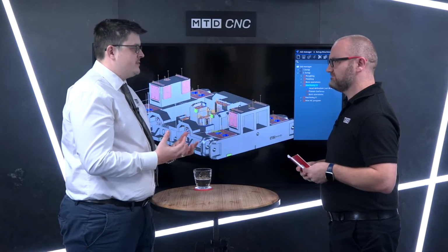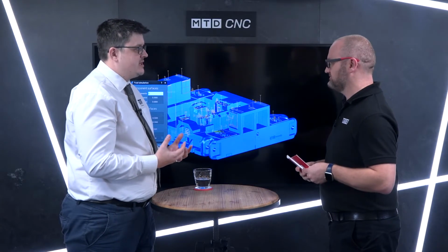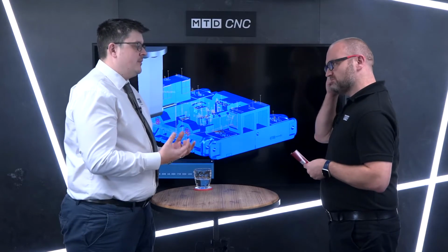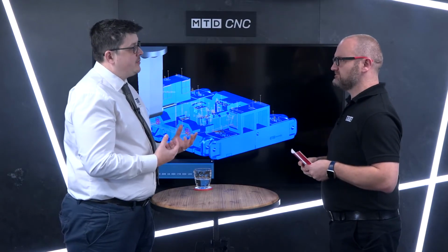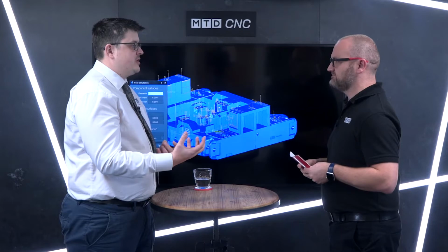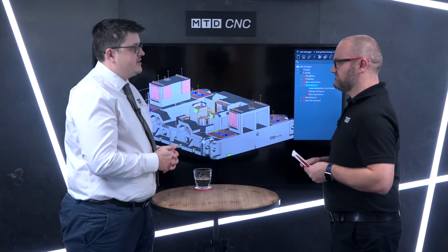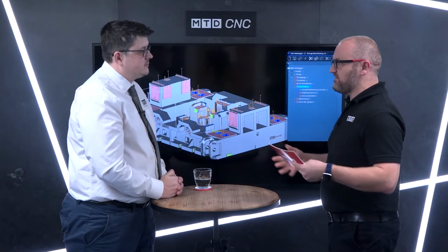So Tebis can use a combination of features and NC sets when we're creating full 3D models, 3D surfacing, and very complex shapes and complex series of operations. In broad terms, Tebis doesn't make much of a distinction between turning and milling. As long as we have a machine that's capable of the process, we create the virtual machine that can do it, and Tebis just carries on and uses the NC sets just the same way. It's just a feature. Just a feature.